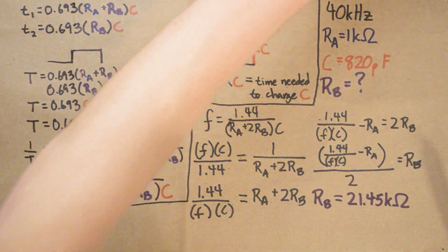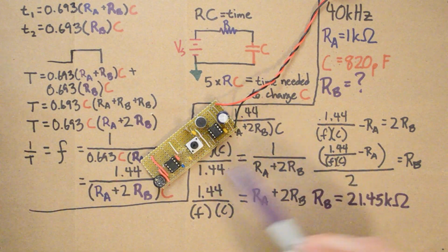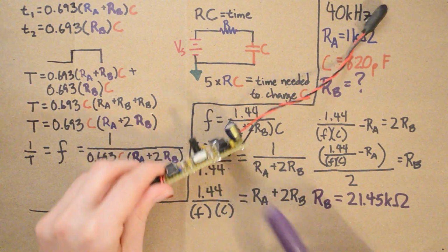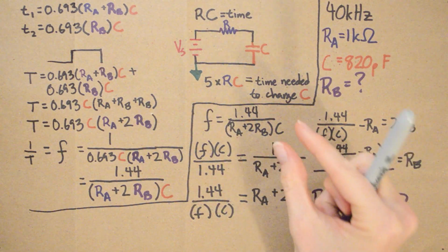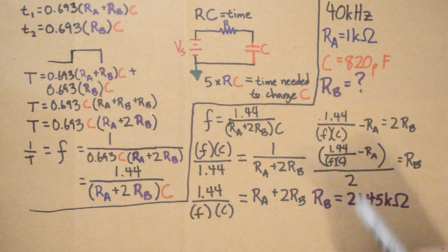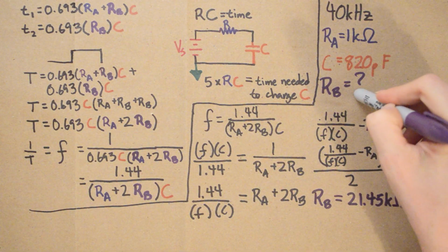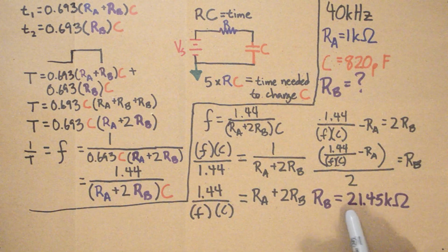No, I didn't end up using it, because what I really ended up using was this large variable resistor right here. Here's the thing about a 555 timer, is you can calculate all day long to try to get the exact values that you need to hit this target at 40 kilohertz. You can breadboard it up, you can get it close, and then when you're all done with it, you take it apart and you put it on a circuit board, and you'll notice that you're always just a tiny bit off.